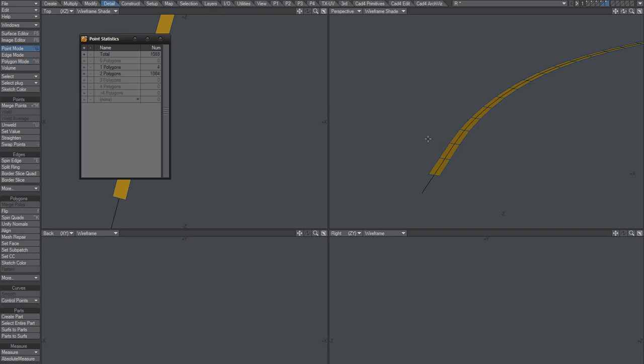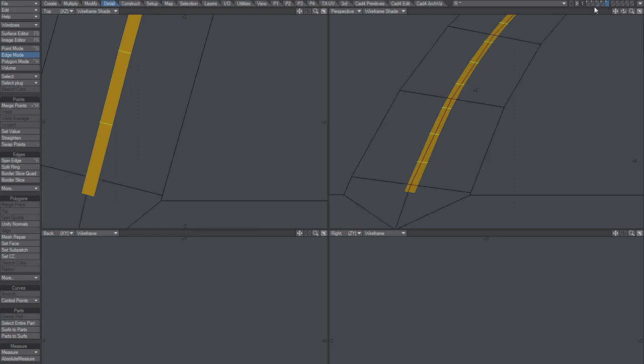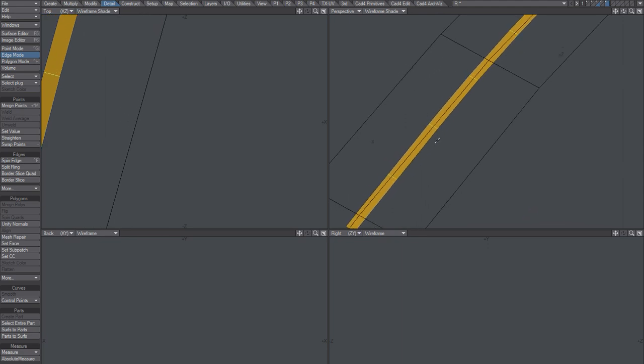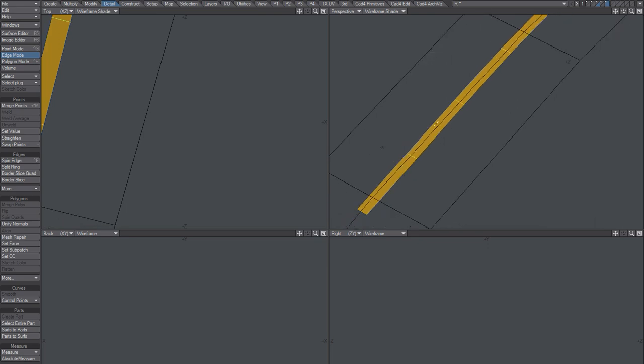What I'll do next is I'll say edge, 2 polygons, click that, and this is where you choose the gap between the yellow stripes. You could copy this to a new layer and do this twice, use background to morph and create an inner morph that will morph between 2 different gap distances, so you can adjust it later on, but I'm just going to go the regular way about it, just create a gap.